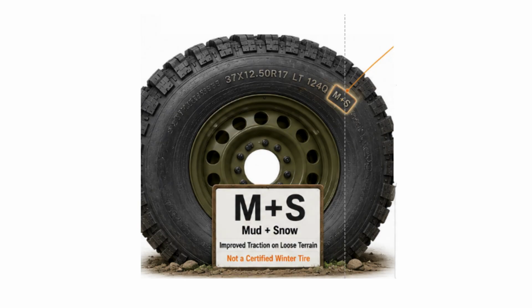This image explains the M+S marking commonly found on all-terrain and off-road tyres. M+S stands for mud and snow. It indicates that the tyre's tread pattern has been designed to provide better traction than a standard road tyre in loose conditions such as mud, light snow, gravel, and soft terrain. This improved performance usually comes from wider tread grooves, larger tread blocks, and more open spaces that help the tyre clear mud and snow from the tread.